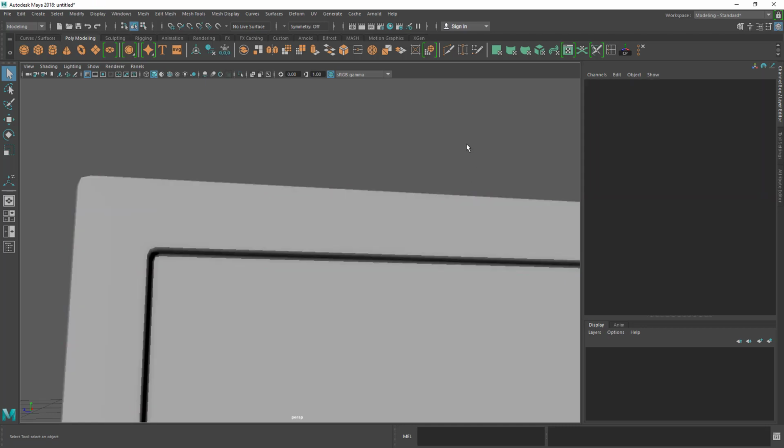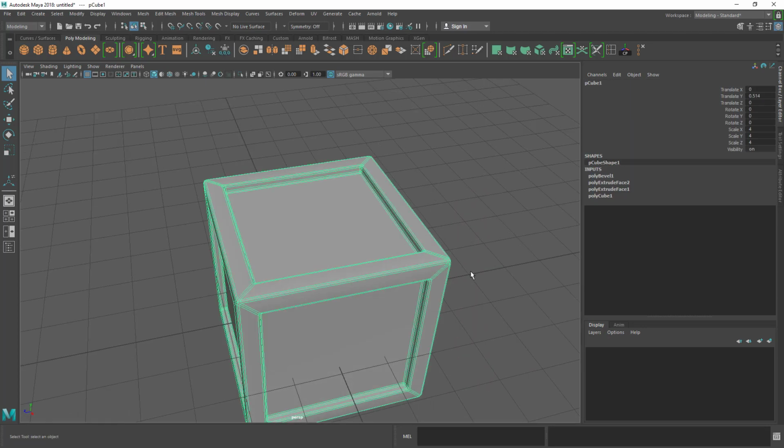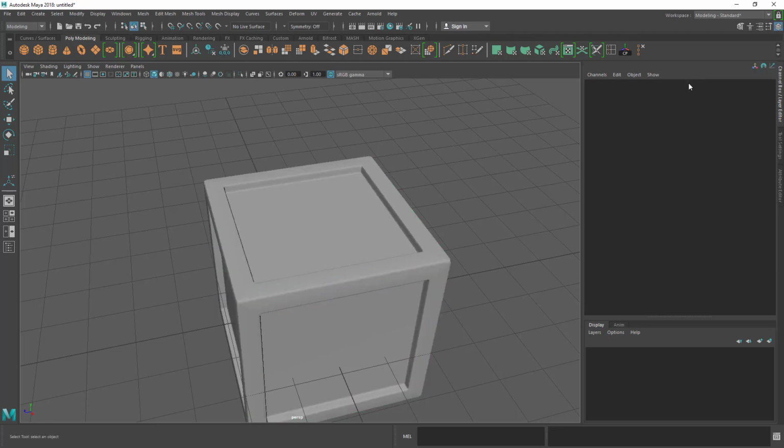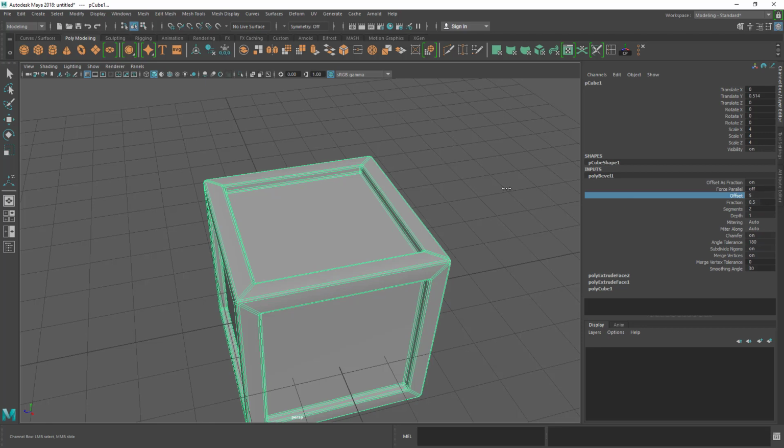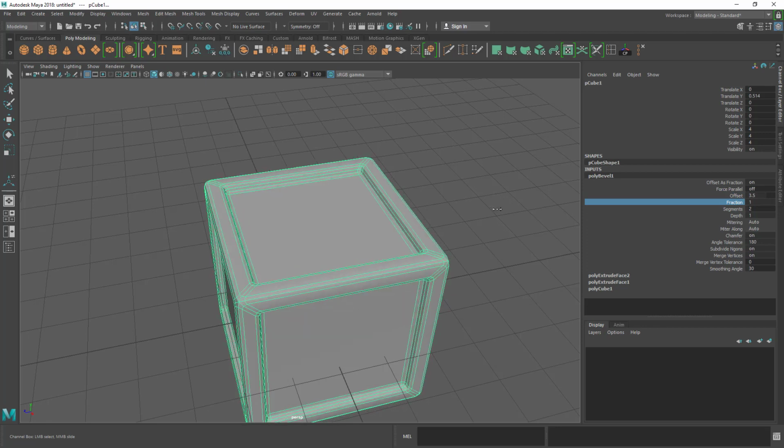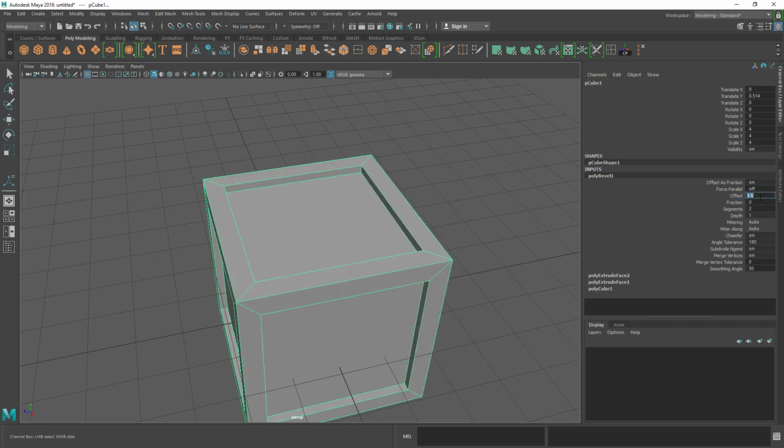And if you lose it, and you go, oh no, I've lost it, but I need to change it, you can click on the inputs, as long as you're in the attribute editor, the channel box. And you click on that, click on the channel box, and it'll appear, as long as there's a blue little halo around it. And then go down to Bevel, and you've got all the options here. And if you middle mouse button it, you can adjust it. See? And we just undo this because we don't want to do that.